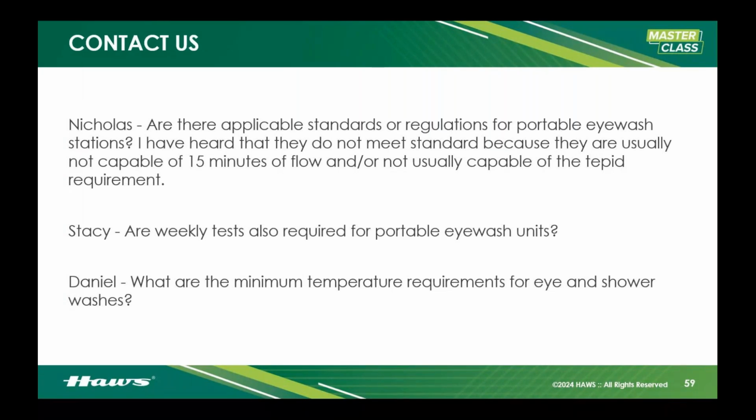If you purchase it, you'll see a section for eyewashes, a section for showers, a section for portables, a section for each type, even supplemental bottles. You'll see sections for every single one of those, portables being one of them. That portable equipment is driven by the same exact standards. The performance of the eyewash, they have to do a full 15 minutes. Now, I agree, there are some weird ones out there that do very little. You're going to get maybe 8 minutes out of it. These are not ANSI Z358.1